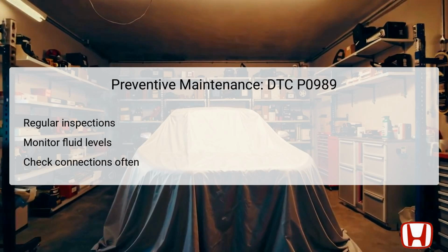Additionally, routinely monitoring the transmission fluid levels is vital, as low fluid can lead to both operational challenges and increased wear on the transmission system. Ensuring that all electrical connections are tight and free of corrosion will aid in preventing electrical communication problems. Emphasizing these maintenance steps will significantly reduce the likelihood of transmission fluid pressure issues and enhance the longevity of the vehicle's transmission.